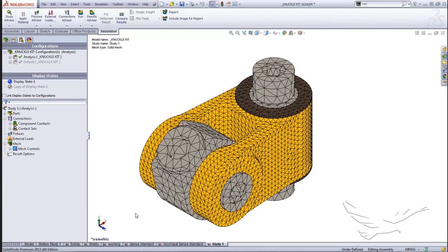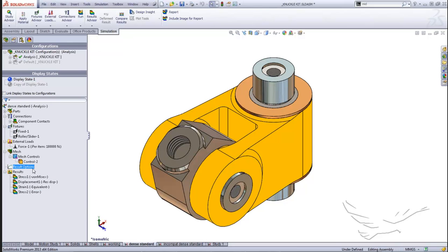So if I say, what, I'm not going to spend an hour or 2 hours to troubleshoot this mesh, I'm just going to go ahead with the incompatible mesh, then you do trade that off with a little bit longer runtime, right? So just how much longer is that? I've got a dense standard mesh and an incompatible dense standard mesh both run.